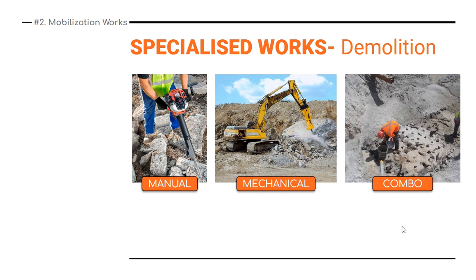Then the last and most effective method is combo. Here you need a rotary drilling machine to drill through the rocks. Then you can employ expansive chemical grout, which will take some time, but after some time it will automatically disintegrate the rock. Okay, so this is the best way of getting your work done. After that you can employ mechanical or manual means to dispose of the disintegrated rocks.